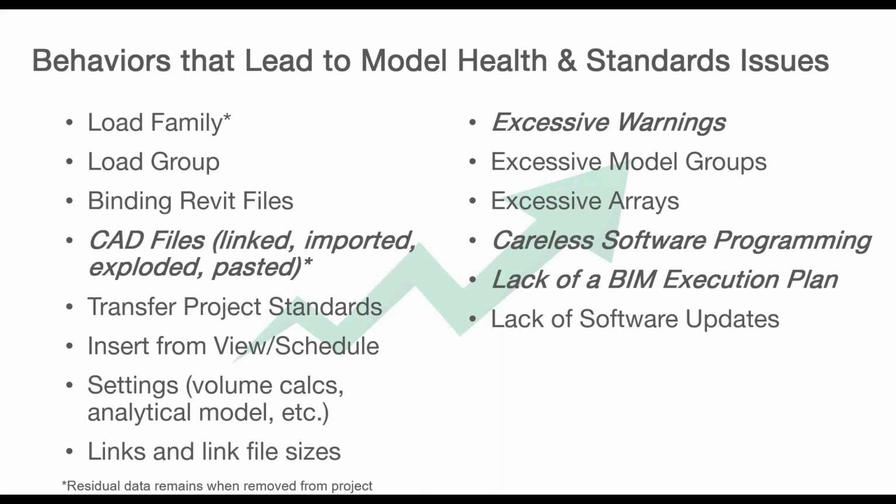Loading rogue families. I cannot stress enough how important it is to vet families before you load them up into a project. Take it somewhere else, clean it up, review it, change things that need to be changed, whether you've got to change parameters, merge styles or do anything like that before you bring it into a project. Loading groups,